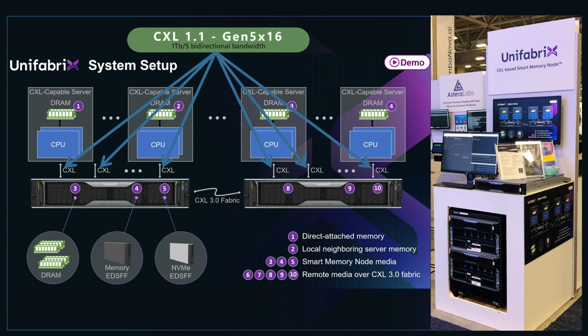My second demonstration will be our SSD over CXL. In this case, I will expose some of the capacity of the Smart Memory Node as a standard NVMe device over the same CXL connection. This device will expose itself as a standard NVMe device to the platform, and we will run standard FIO testing to explore its performance.